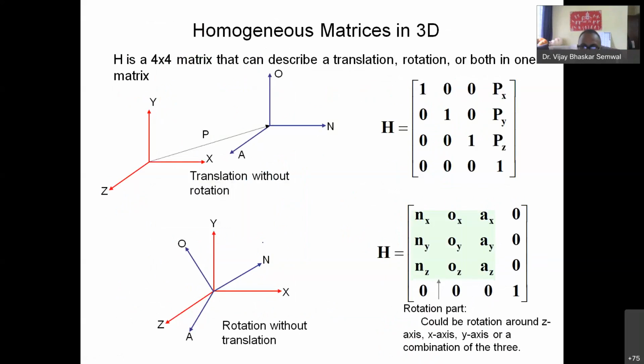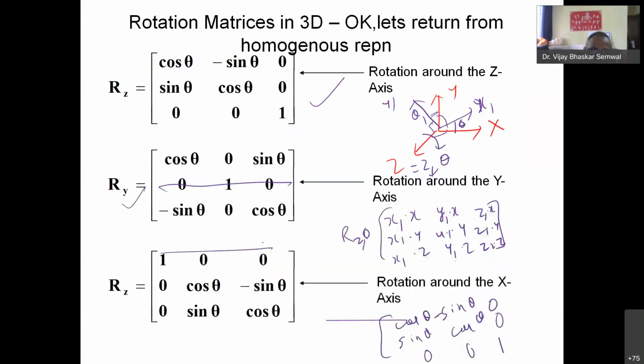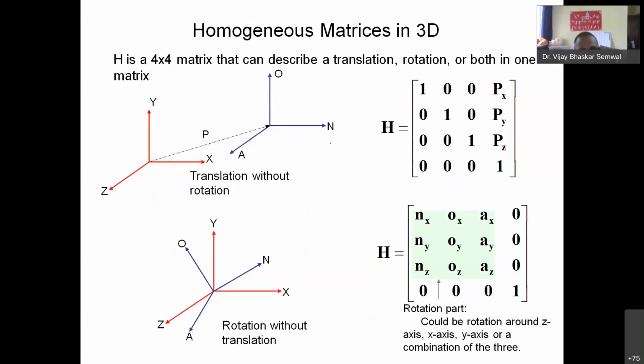Okay, now you have to merge rotation as well as translation. So what you will do, singular matrix, I need to prepare a homogeneous matrix which covers translation and rotation. So for that, what I did is I merged them. First this block is kept as a 3x3 matrix for rotation, and one extra matrix I have created for the displacement around the XYZ axis. So this is the rotation matrix and the displacement matrix, multiply both.